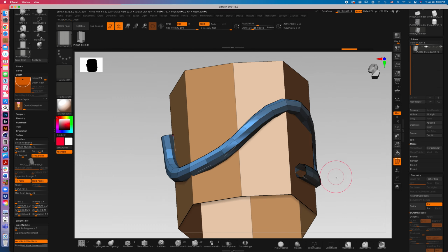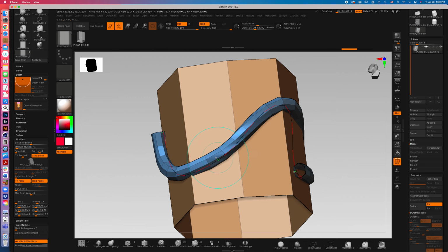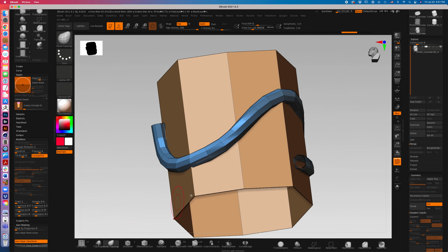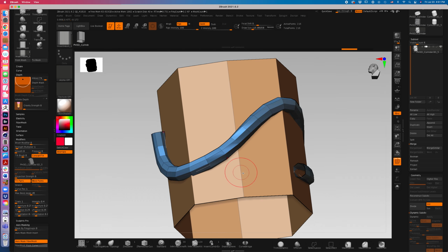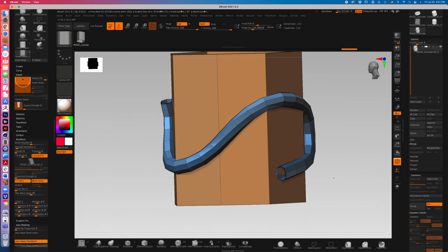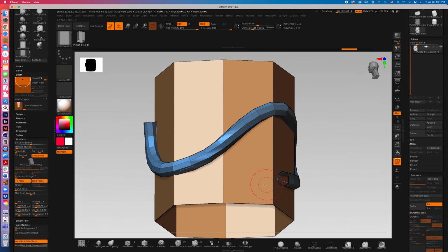Lastly, how do we accept this? How do we make it just happen and be polygons that we can use and bridge and do everything else with? The way you do that is you just click off the object on another object, and that will remove the path, and now it's there. The trick is that if you switch tools, if you switch to the Move tool and click, it's still there. That was very confusing for me when I started. The only way to drop that is to do something like this, and then click on it like this. Now these are just polygons.